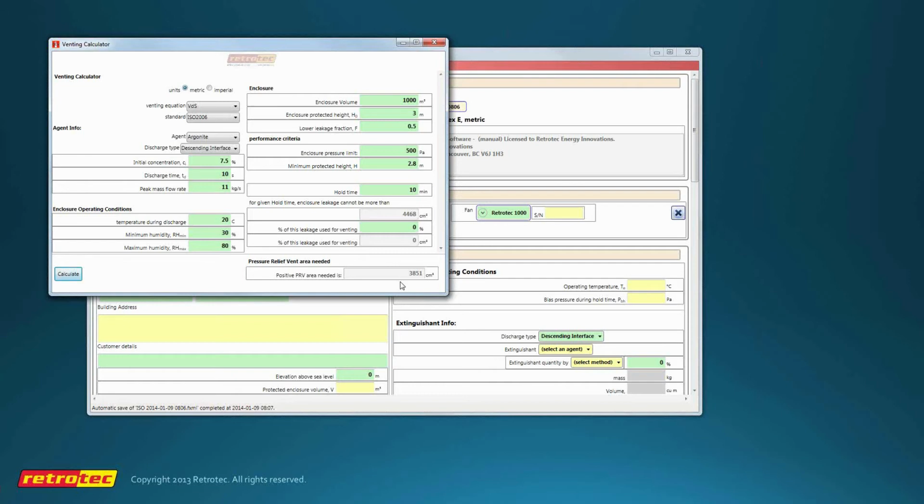Obviously, when it's connected to ductwork and so on, that free vent area will be reduced, so whatever you measure in this box will be the maximum free vent area that you would ever get. But if you're venting right through a wall, then you would get that at least through the vent, and then you have to measure the rest of the vent path.